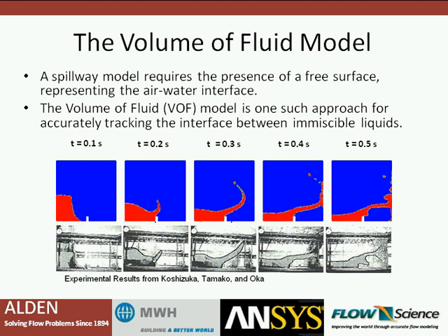So inputs to the VOF model include standard material properties. Users can input into the code things like density and viscosity. And you also need to declare the boundary conditions for the problem. So this may be any combination of 0 or no slip velocity conditions on the walls, the presence of a symmetry plane, as I showed in the previous slide for the geometry setup, time-dependent inflow conditions, pressure outflow conditions, and the like. After you do this setup, you can submit the model to the solver.